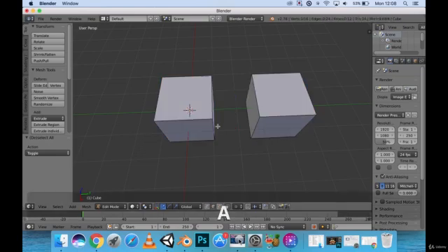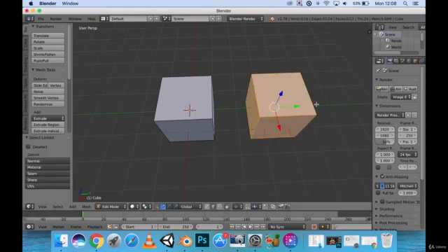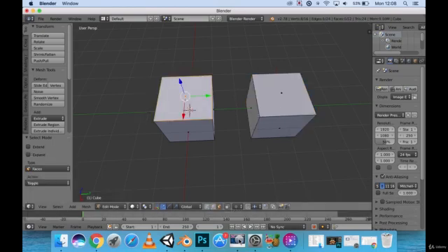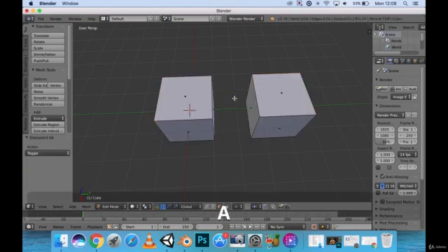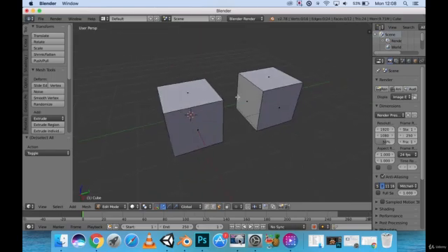Instead, I'm going to deselect the objects here by clicking A. I'm going to click L instead. L is going to just simply select the island area that you've wanted. Let's go into face mode actually. Grab this, click L, and click L again to select that. And deselect. Pretty simple. A and L. And yeah, that's pretty much it.